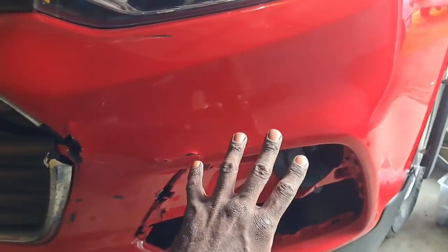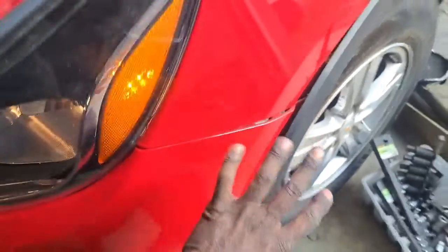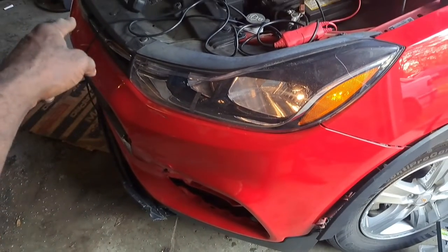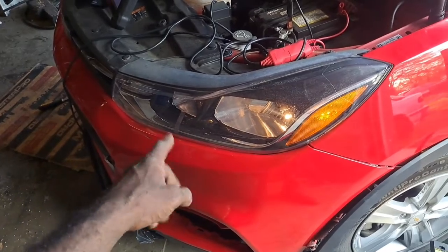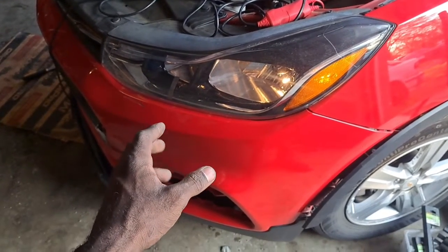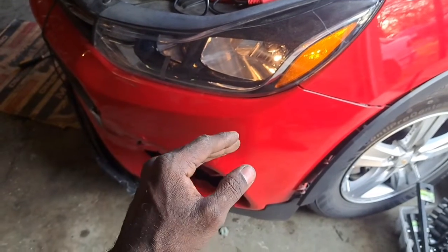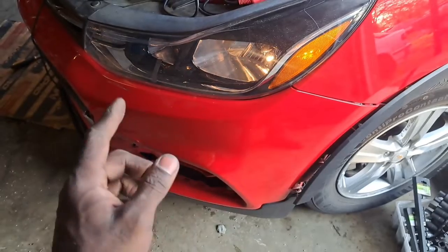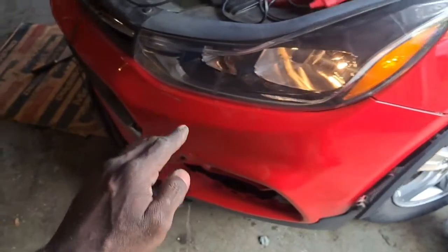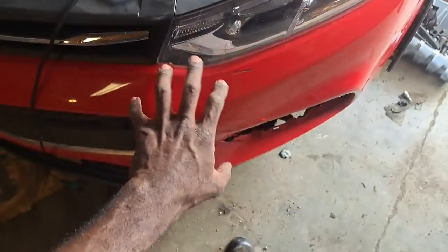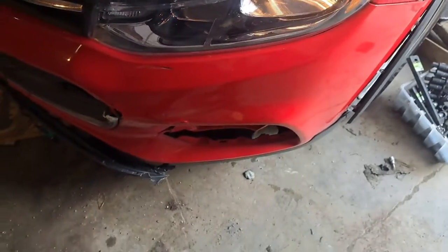So I'm gonna pull the bumper off, and then we're going to look at the wire, because that's a sub harness from the sensor to here. There's a sub harness that sits on the bumper support, and we're going to try to jump the signal wire and see if it changes. If it does, then our issue is going to be from here through here, or in this vicinity. So let's pull the bumper off.